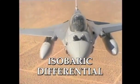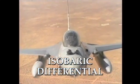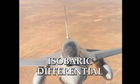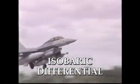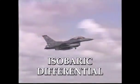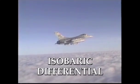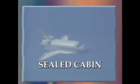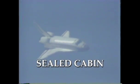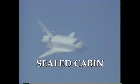Isobaric differential. This type of system is used mainly in military fighter aircraft because the isobaric system is too heavy. Upon ascent, the cabin begins to be pressurized until it reaches a preset altitude. If the ascent is continued, a constant pressure differential is maintained. Sealed cabin. This system is used only in spacecraft that carry their own supply of gases to create the pressurized environment.